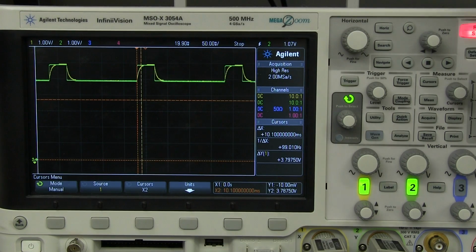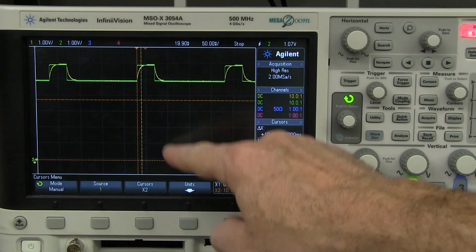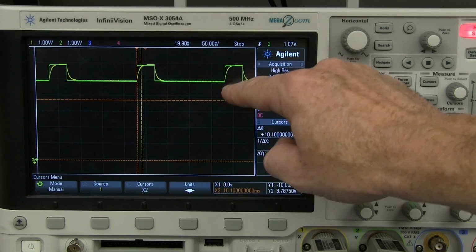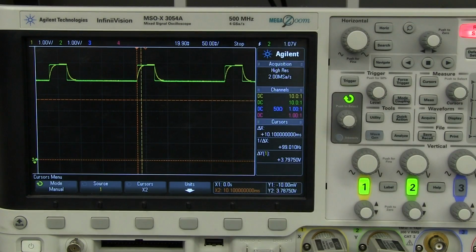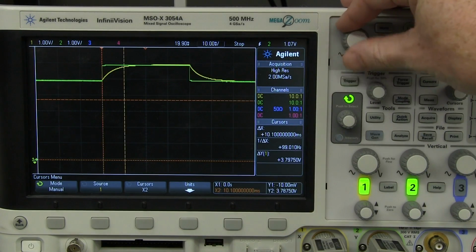So if we do our single shot capture, there we go. There's our ground level down there. It's still exactly the same as before. 1, 2, 3, 4, 5 volts. But now our waveform is superimposed, biased 5 volts up. But hey, that should not affect our formula at all. The time constant doesn't matter about what the initial value is. It's all about that step change. It makes no difference. Trust me, the formula ain't wrong. It's been around forever, and you can rely upon it. It's 100% correct. So let's go in and measure that, shall we?